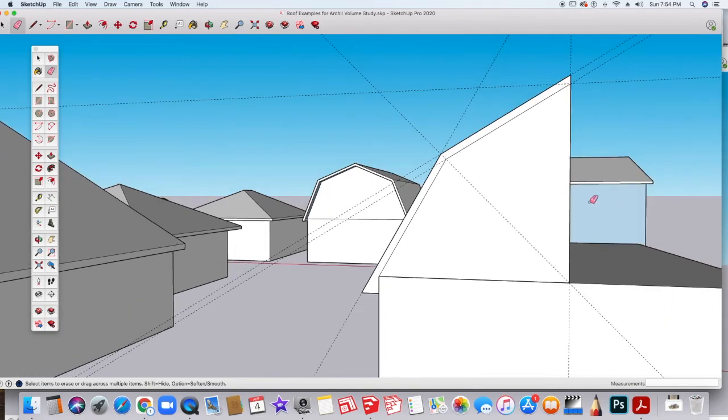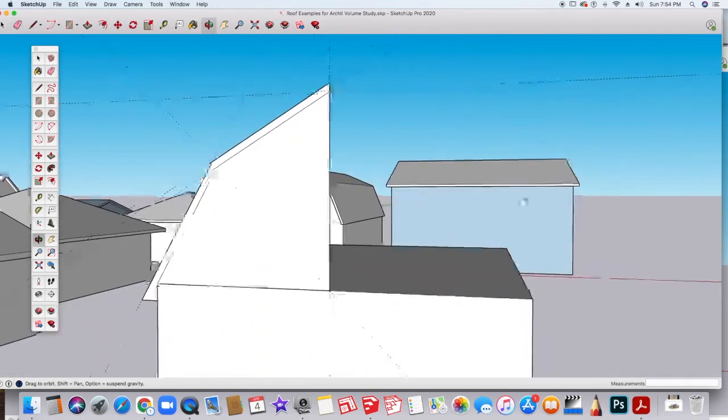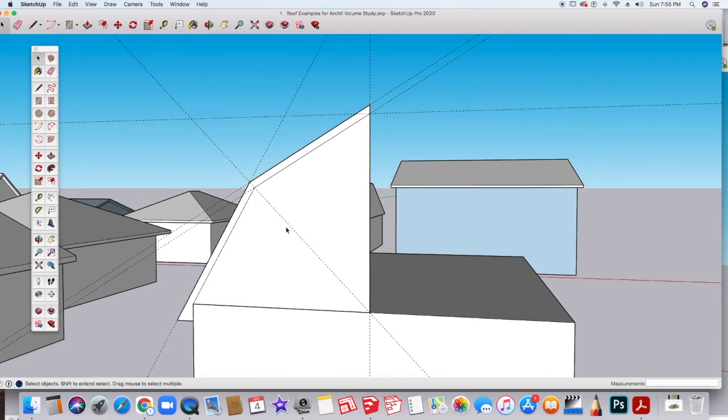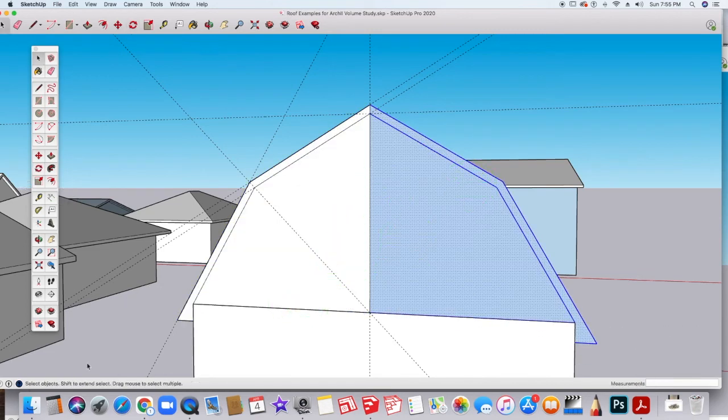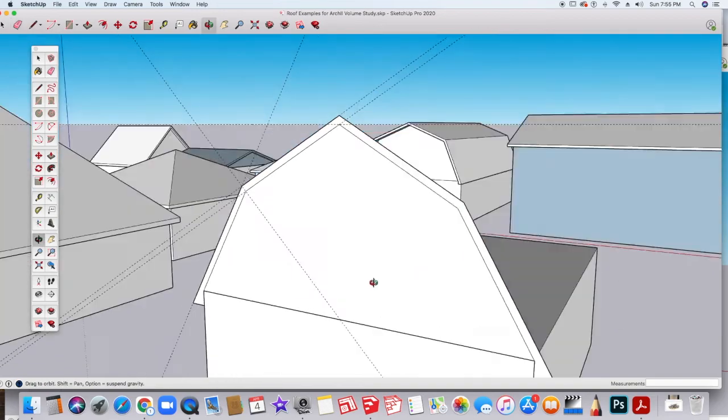We're going to do the same thing that we did when we did the open gable roof. So here, I'm going to triple click the inside. I'm going to use the rotate tool, let it snap to blue right there at the 90-degree angle. I'm going to click, click away to make the arm, and click again. And now I'm going to hold the shift key and pull that copy directly across. Then I'm going to click away to deselect and delete these lines. There we go.